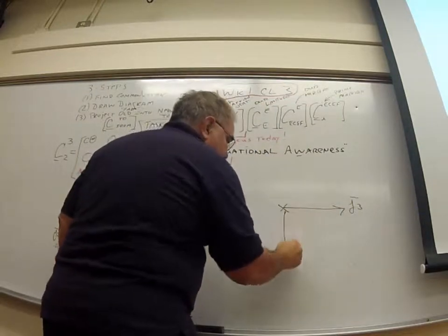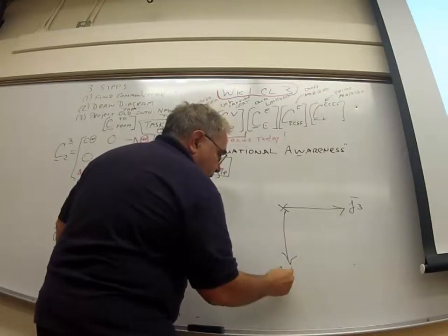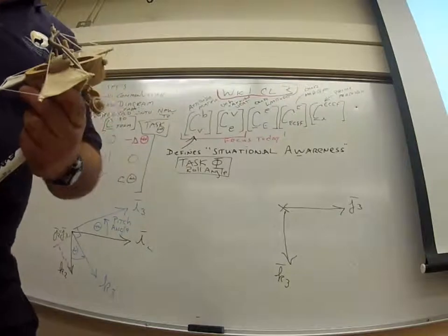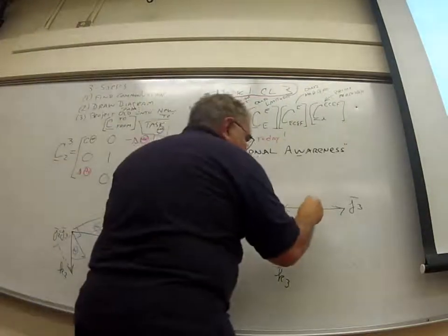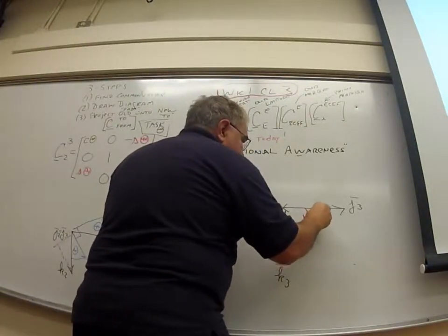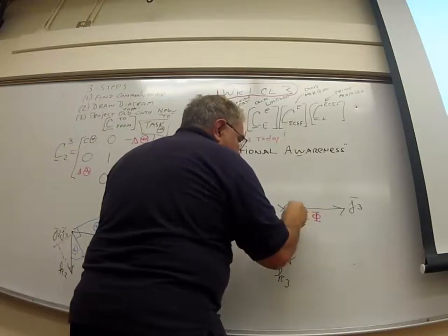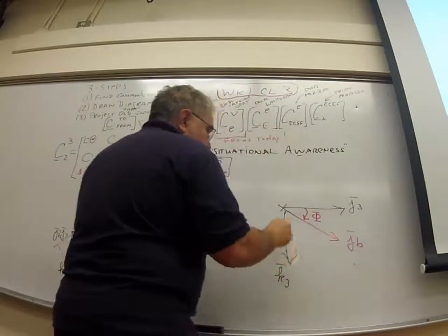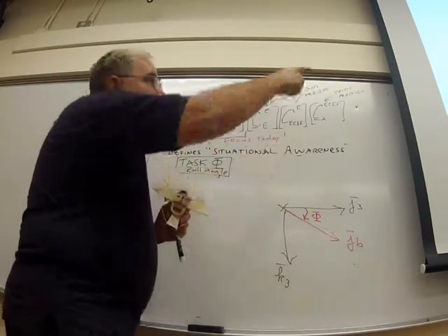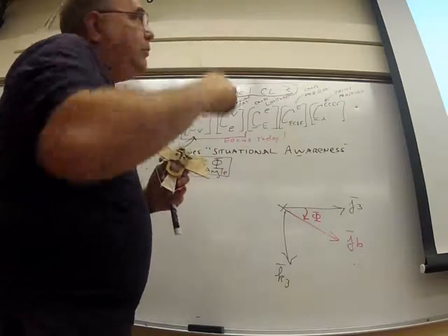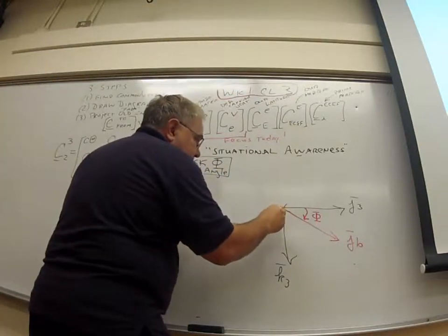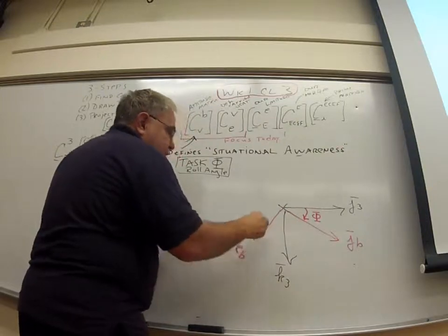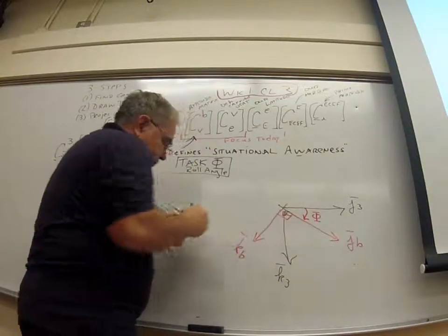Of course, I'm going to have K. This is going to be K3. And then I'm going to rotate through roll angle phi. We're just going to rotate through roll angle phi, and that's going to give me JB out the right wing. And of course, the K vector is going to rotate. K is rotating in the cockeyed plane up there, but it's going to end up KB. And KB, of course, is defining down relative to me.